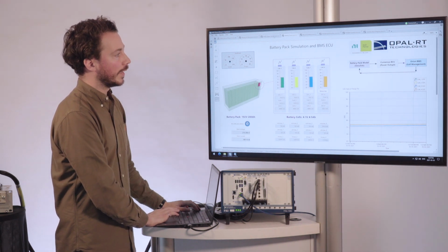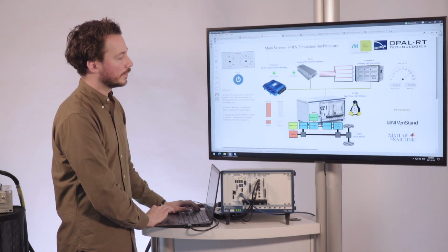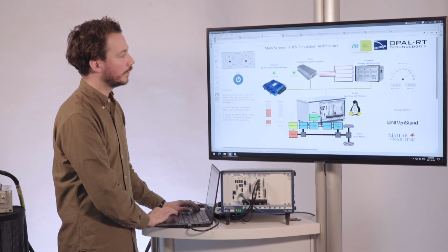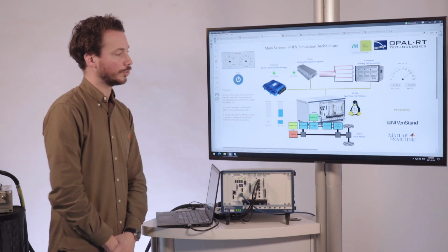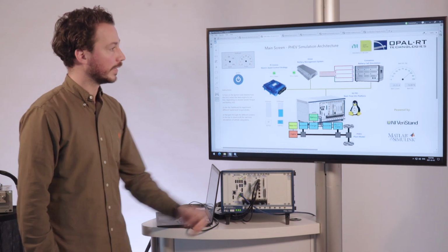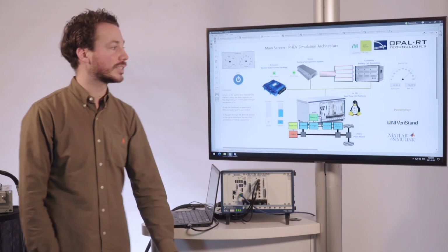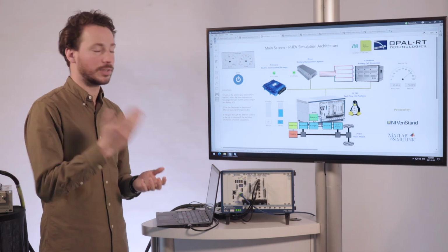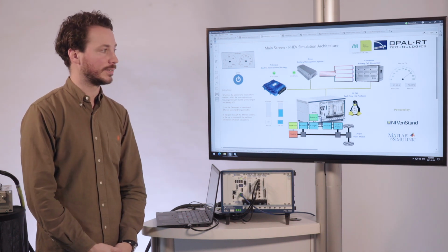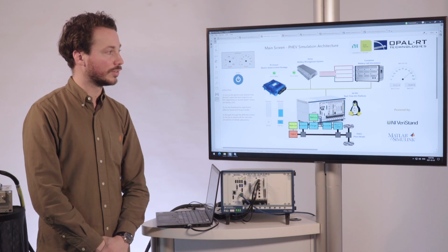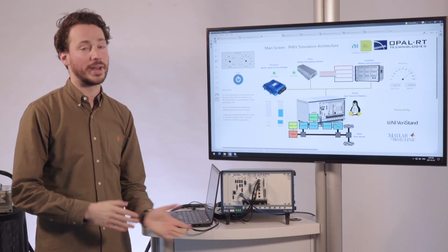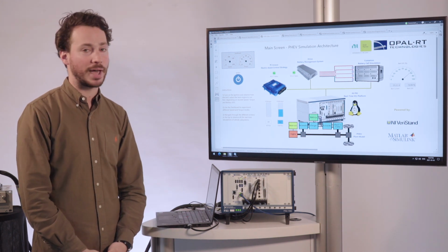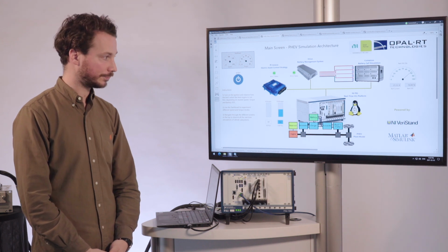So with that being said, I will go back and turn the torque a little bit lower and the speed as well. So now we've gone back again to the electric machine. The electric machine is now pulling a positive amount of current, so it's discharging the battery. And now we can let this run basically to be able to see if our state of charge will go down and have our BMS control when it's time to charge and not deplete the battery completely.